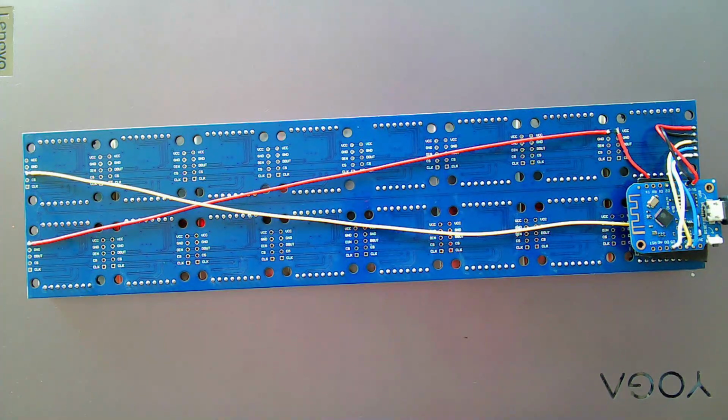Fitting to the horrible code I wrote, this is horrible hardware I did. The PCB, as you see it over here, has a big ground plane, so I wasn't worried about the ground plane here, but I wasn't sure if the VCC would be fine. So this is a red wire you see here going right across the board and supporting the VCC on the other side. I haven't tried the circuit before, so maybe this is unnecessary, but I did it anyway. The yellow wire you see over there is the data out from the upper left corner to the lower right corner. You have to move this over there because otherwise you have a connection between the two rows.